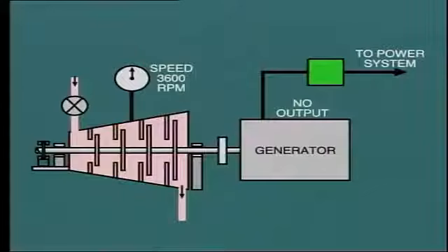Of course, the turbine generator would immediately increase speed because at the instant of the breaker trip, a very large quantity of steam is flowing through the turbine. Under normal circumstances, the governor should be able to close the turbine control valve sufficiently to bring the speed close to normal within a few seconds. However, imagine what would happen if the governor failed to act properly,